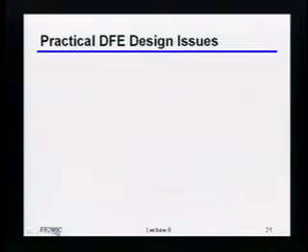Okay? So sometimes even when you do that, of course, you're still going to want to do a DFE. So you just need to keep track of when you start doing these interleaving things. That's going to interact with how you end up building the DFE. So the key thing to keep in mind is that, generally speaking, the settling constraint on the DFE doesn't really change. So if you start doing interleaving, at some point you may actually be just spending more power without really saving yourself anything in the comparator itself.